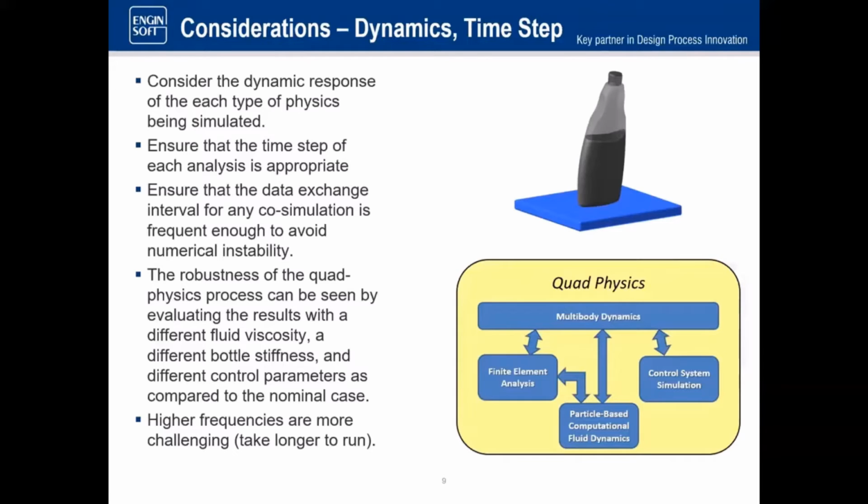But as far as time step for the structural analysis, that's really determined by the material properties, modulus, and so forth. The stiffer the structure, the higher the frequencies that may occur in it, and therefore the smaller the time step needs to be.